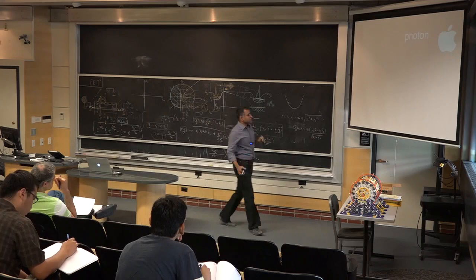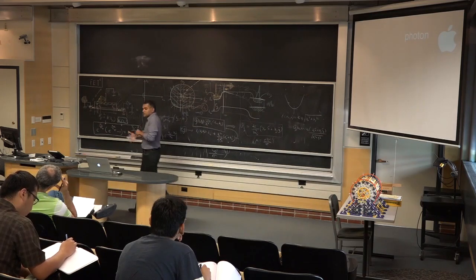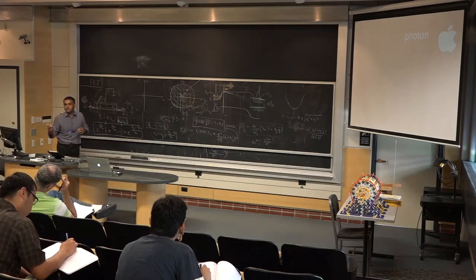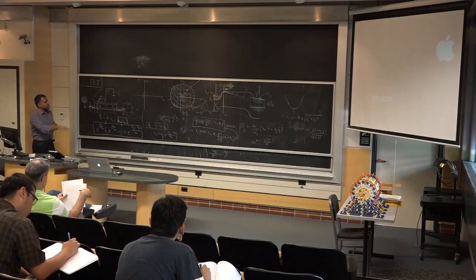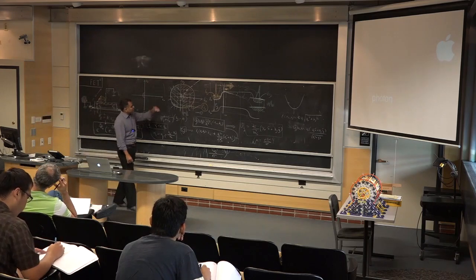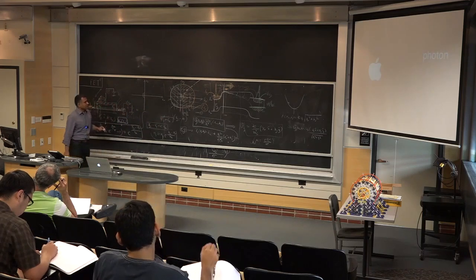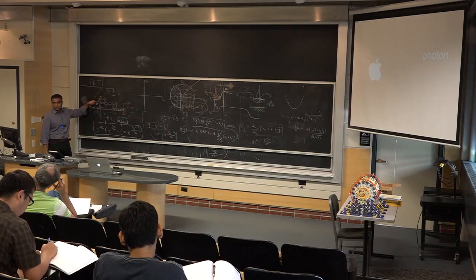If the gate cannot control how much charge is in the channel in the FET, then it's not really a FET. Many times people will show these devices where the claim is FET, but you can ask how much control the gate has. What we'll see is you get all these short-channel effects and so on. That's all because the gate has lost control over the channel.